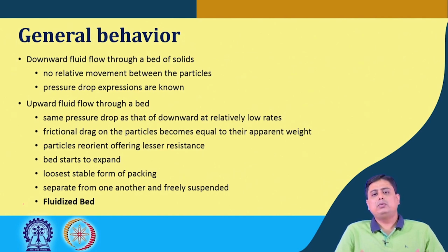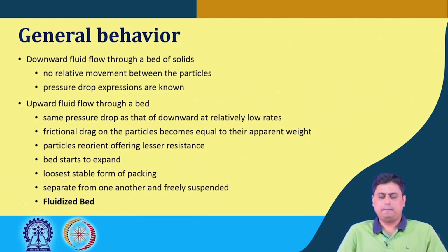As we increase the liquid flow rate, or let us say the gas flow rate, or in general the fluid flow rate, the frictional drag on the particles becomes equal to their apparent weight, and that is the critical condition based on which we solved one problem in the last section. So as you increase the fluid velocity, there will be a point when the apparent weight of the bed of solid particles will be equal to the head loss or the frictional drag on the particles,